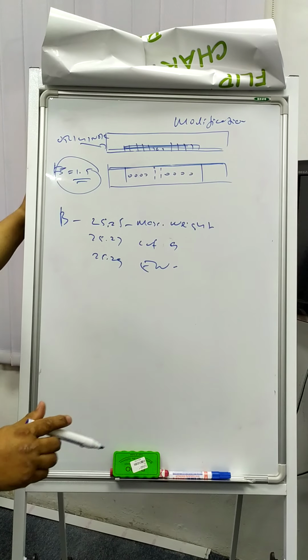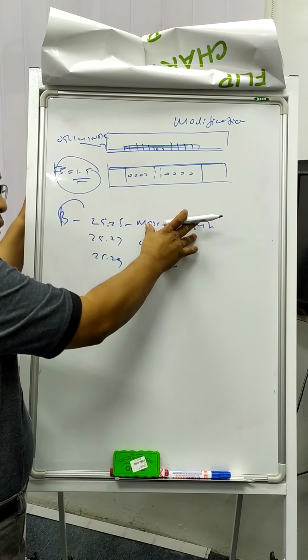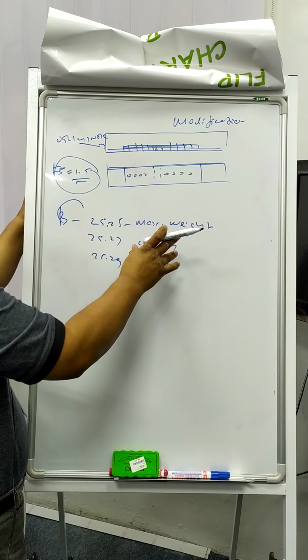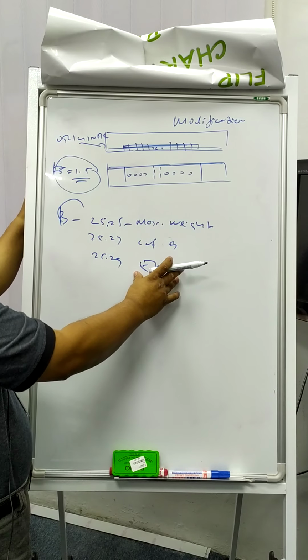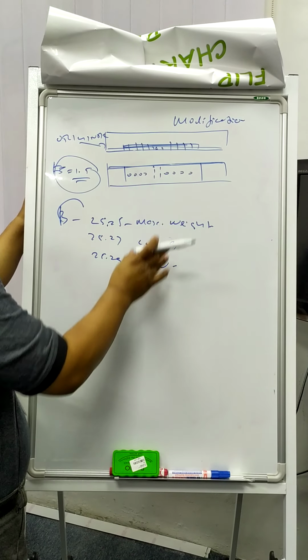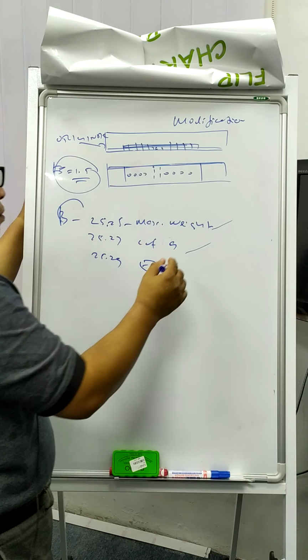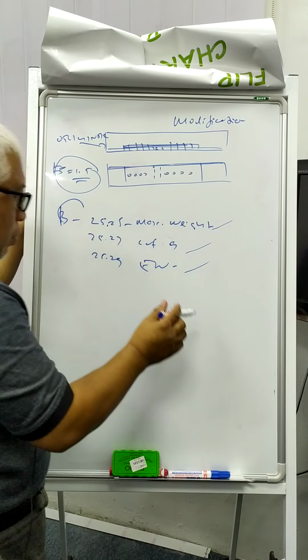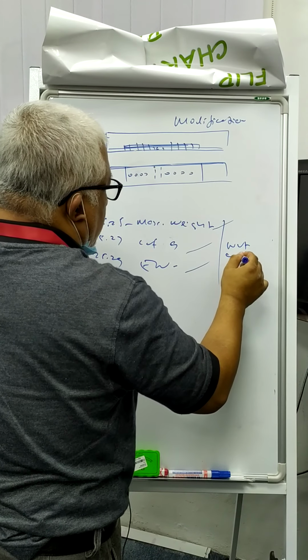Now you look at your repair. Does the repair change the aircraft weight? Does it change the CG? Does it change the empty weight? For this small plate, I don't think we change the max weight, the CG, or the empty weight. So after review, we can consider this not applicable.